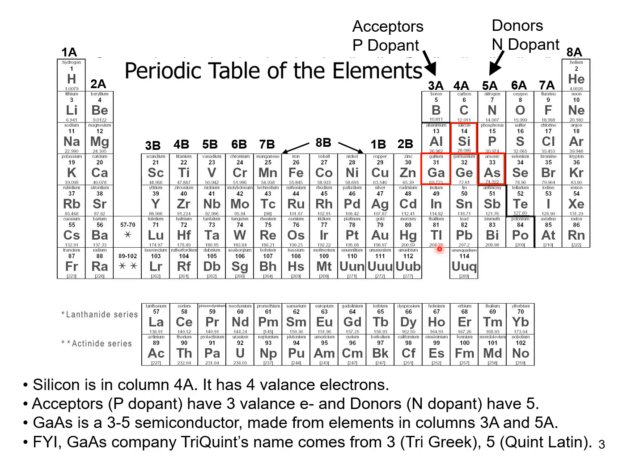That's why it's called a positive dopant. The column immediately to the right of silicon, that's column 5 on the periodic table, is made up of nitrogen, phosphorus, arsenic, antimony, and bismuth. Those are called the donor dopants, and they have 1 extra electron or 1 extra negative charge, so they're often called N dopants.